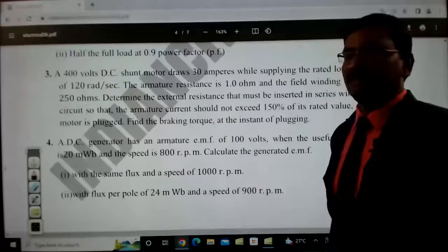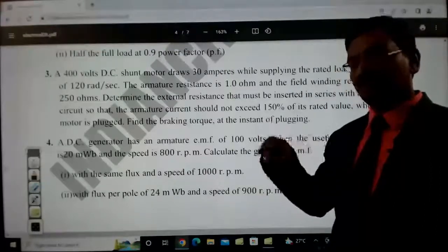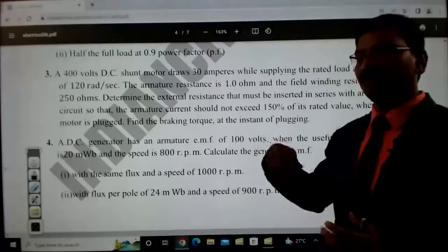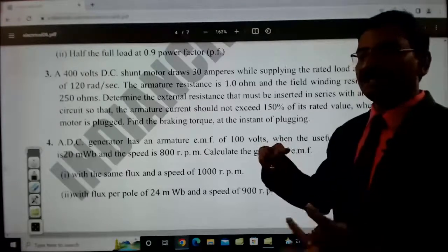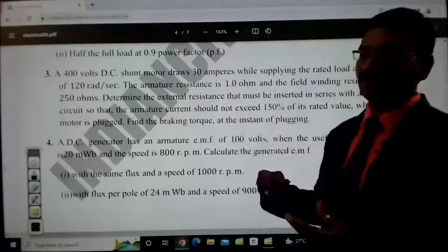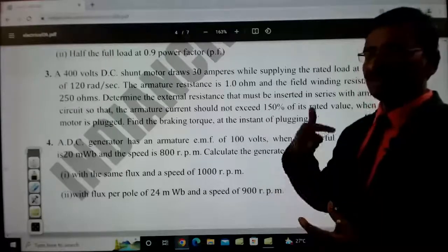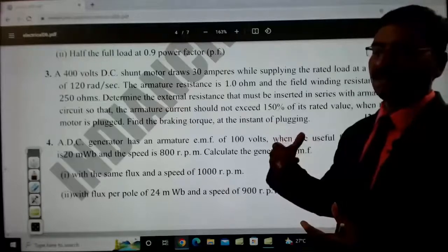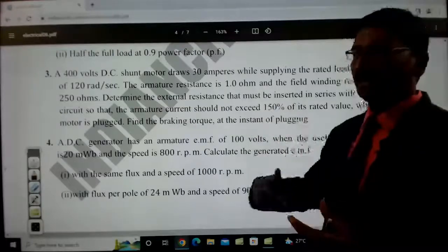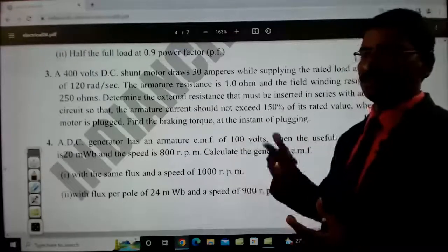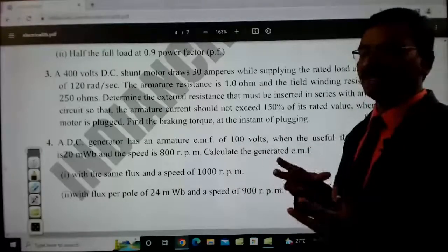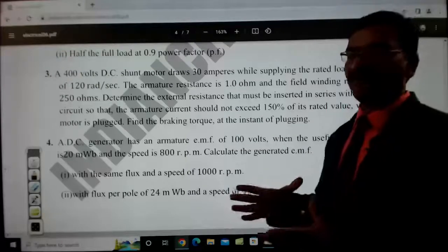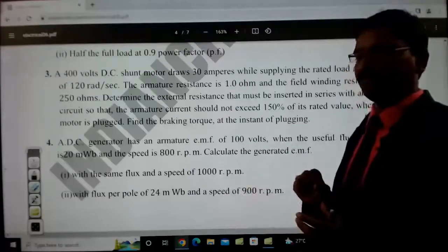Suppose the motor is running in one particular direction like this, you will change the connections of the motor while running in this direction, so that it wants to run in the opposite direction. Earlier it used to move like this. We have applied a reverse torque electrically, then it will reduce the speed to 0 and try to start in the reverse direction. But we will catch the moment when it was exactly at 0 speed, and we will hold a mechanical brake over there, right?